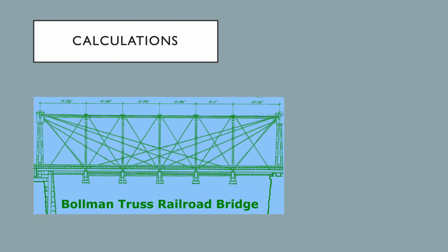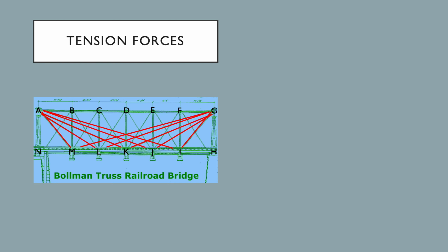I'll begin by identifying where we will calculate our values from. The tension is found in the 10 cables over multiple lengths spanning the bridge. On official documents, these are labeled B1 through B10, left to right. The cable diameter value will be found from analyzing cable B1 on the very left side of the bridge. We will then find 2 critical loads from cord BC1. There are 6 wrought iron cords on the bottom of the bridge, officially referred to as BC1 through BC6, left to right. We will first find tension in the bridge's 10 cables.